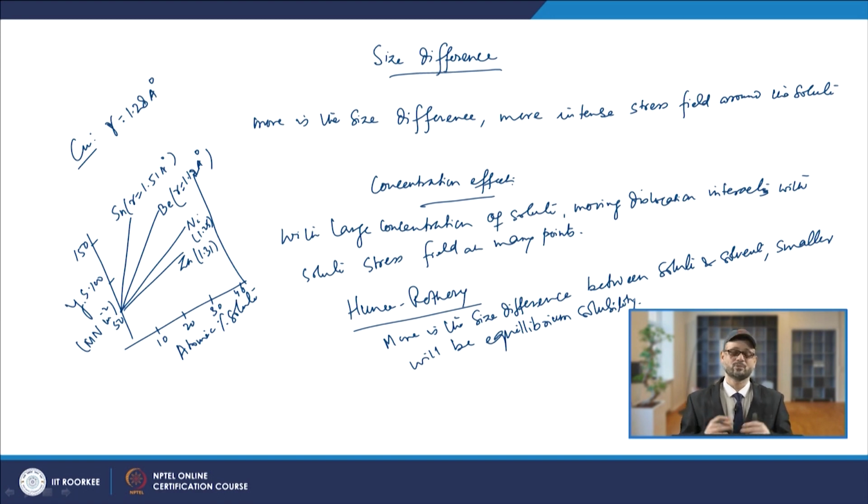There again you have the tetrahedral void, and you have ferrite in those cases. What you see is that the void is smaller than even the size of the carbon. So in those cases the interstitial solute atom, carbon, plays an important role in the strengthening of steel.